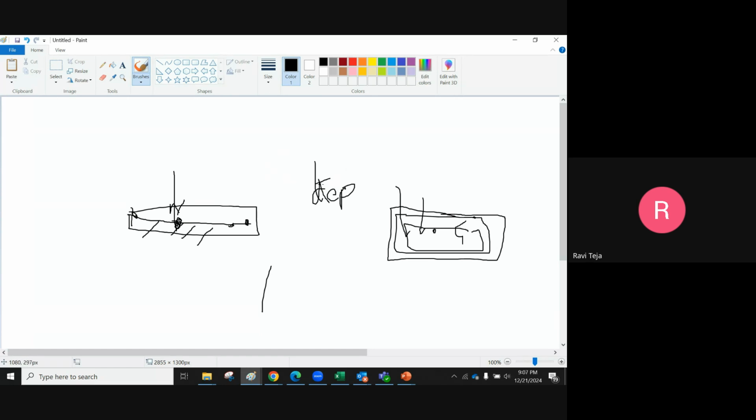So by this what we can understand is, if we have some common centroid device, A and B, you cannot simply place A here and B somewhere else, and then near to B if there is some inductor, the inductor will have extremely high currents. That means more temperature around this thing, which means the speed of this device will be changed.